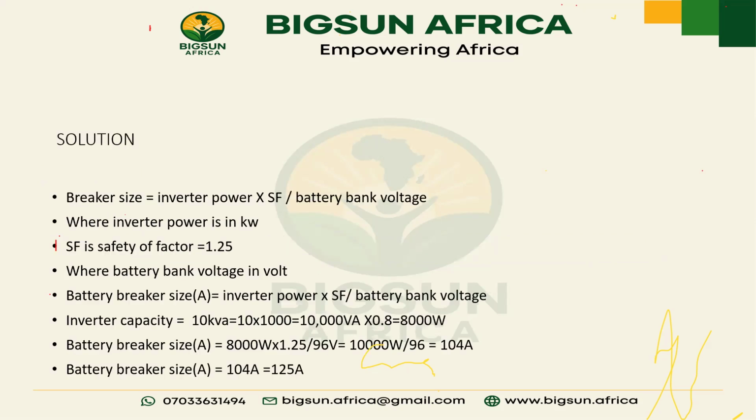Okay, so we've done this calculation, and we got 104, right? There is no 104 amps in the market, so you are going to get around 125 amps. I made mention of that when we got that 130, right? So there is no 104, you go for a higher one, which is 125. Okay? Yes, sir.